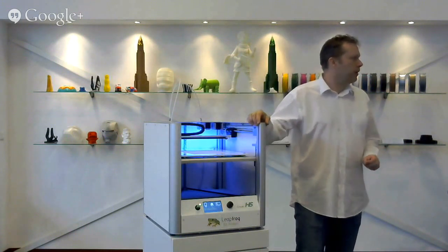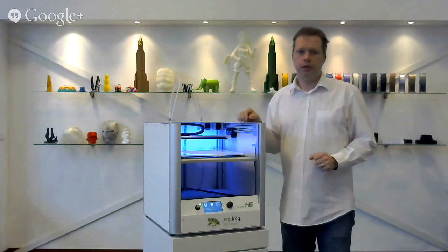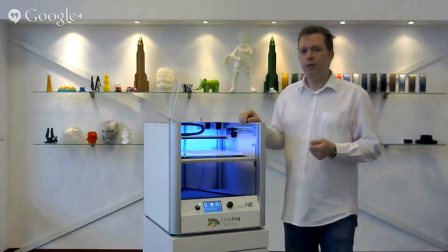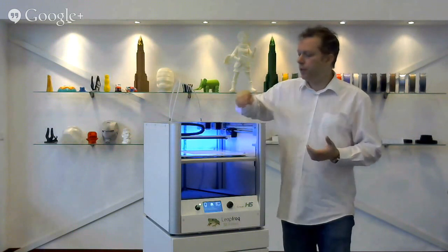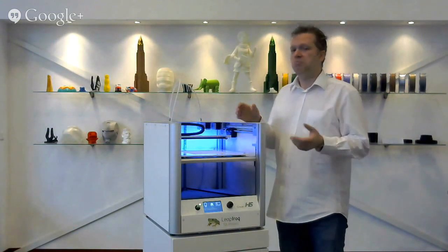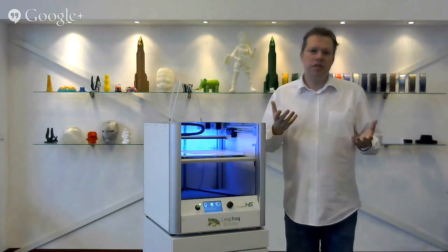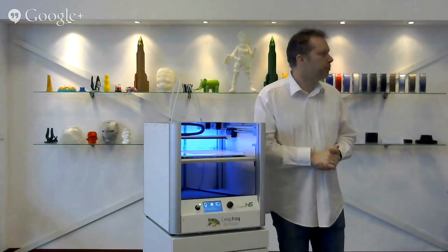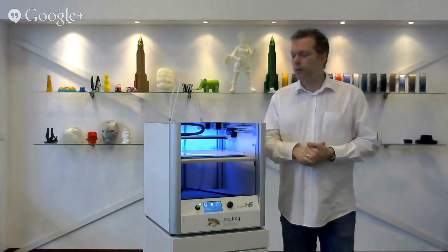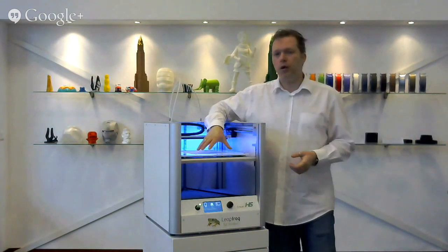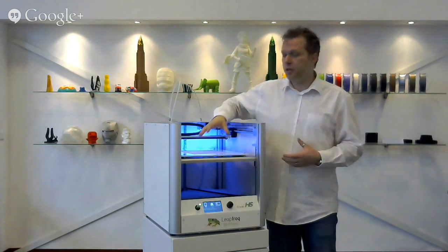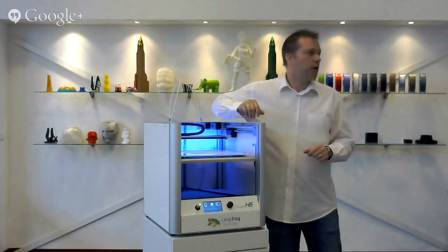Another famous one is ABS sludge. People use nail polish remover in combination with ABS and make a sludge and smear that on the bed and use that as an adhesive. You can do that, but for me personally, I think it's really messy. Another one is wood glue or glue stick, and use that on the bed, but also it's pretty messy and I wouldn't recommend it. My recommendation, especially the print stickers, they work the best.